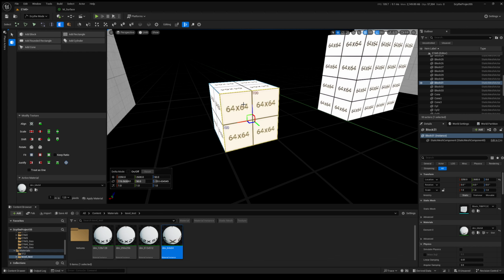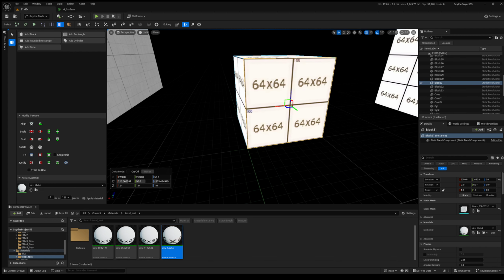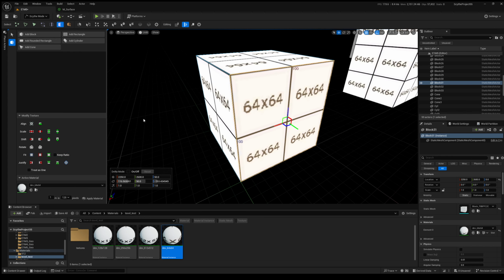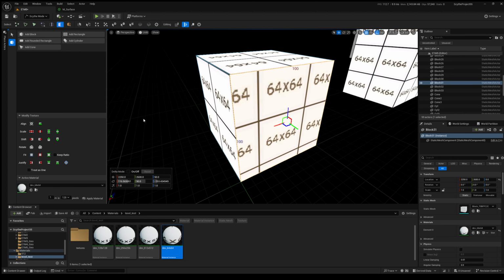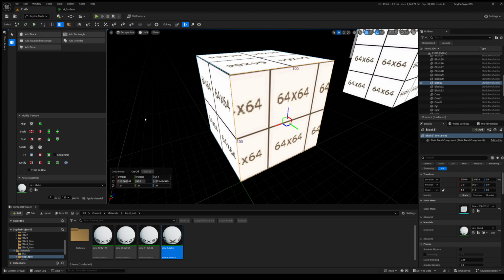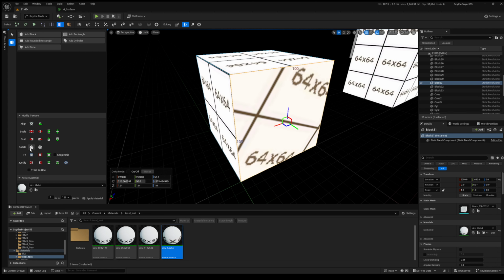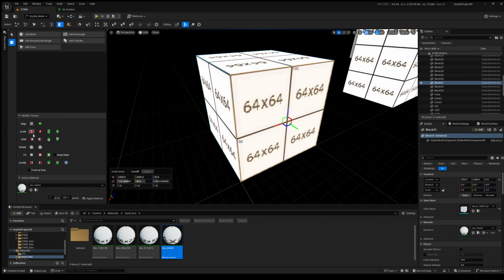So I'm going to show you some texture manipulation here. If I just select one face, I can shift these things around like this. You can also do Alt and the arrow keys, and you have to keep your mouse in the viewport. You can do that real quick. You can scale it, you can rotate it. The rotation goes off of this here. So if I set that to 45, let me reset this. If I set this to 45, I'll move 45 at a time.